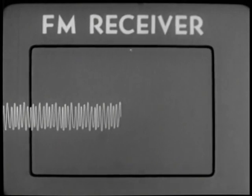The components of the FM receiver are a bit more complex, for they have an additional factor to contend with. The incoming carrier contains intelligence in the form of frequency variations. But it also contains amplitude distortions, hash and static. These we do not want. Since these distortions are located along the amplitude peaks of the carrier, we can eliminate them by eliminating the peaks.